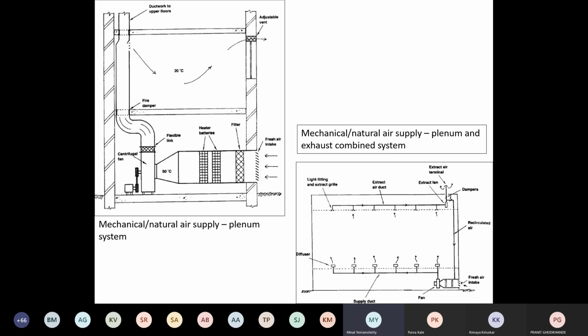Now, I'm going to also tell you what are the various fans that are available. But a centrifugal fan has a kind of velocity that you can't stand in front of it, because the velocity is too much. It pulls things. So the other reason why I cannot have it at the window level of the basement is because with the wind it is going to pull all kind of dust inside. It will pull everything. If there is a dustbin lying outside, everything will be pulled inside because the velocity is huge. The kind of power that thing has for sucking in is terrible.